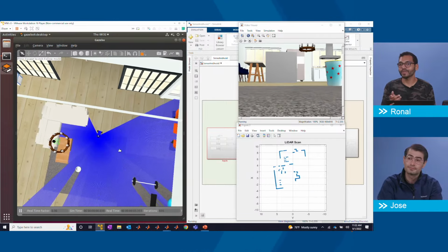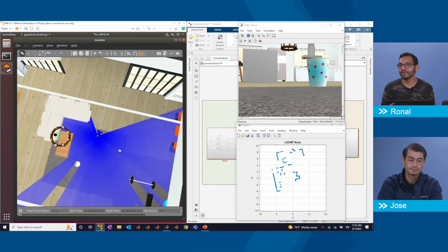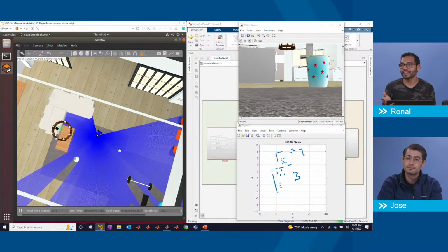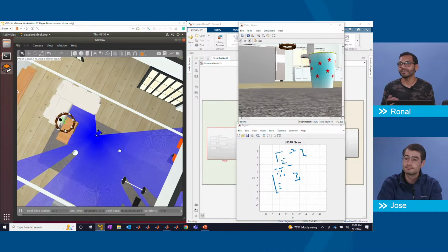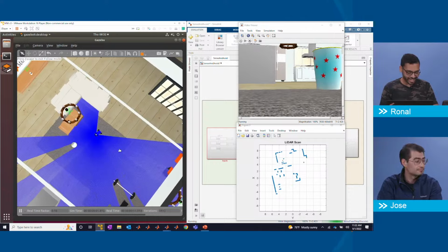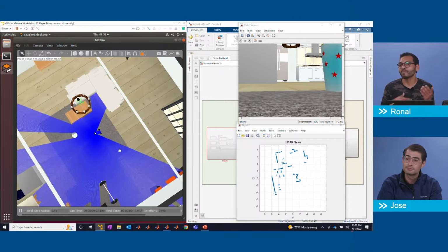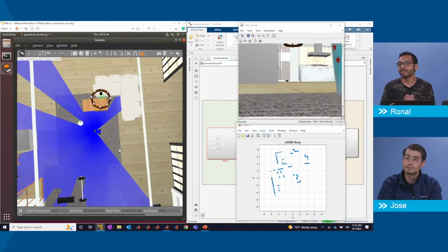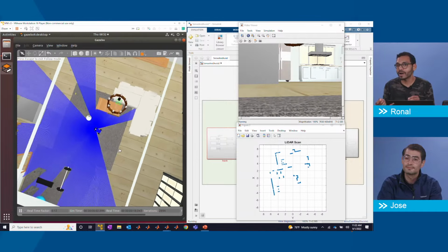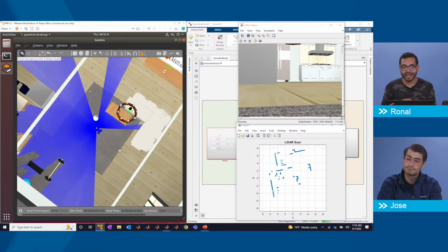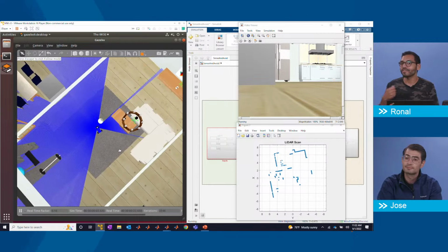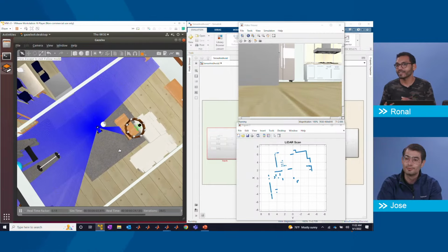Yeah, and the real cool thing about this is, you saw I was running the algorithm. I'm still running the algorithm. And at any point, I can just hit reset. I can hit reset and make sure that, well, maybe I'll try it again. See, with a couple different parameters, I'll tune my LiDAR to have a different safety distance, a different range for actually looking at data.